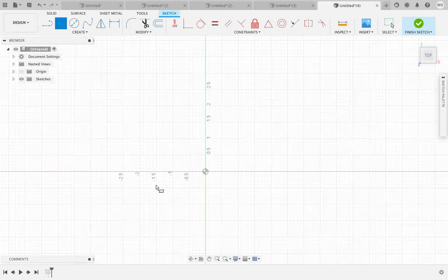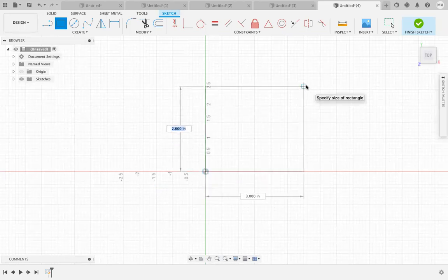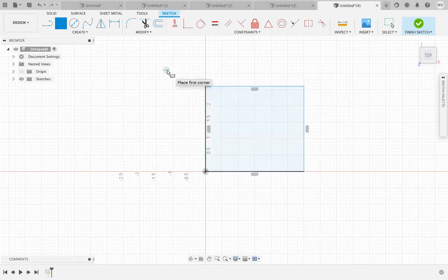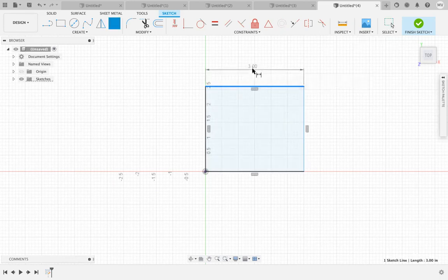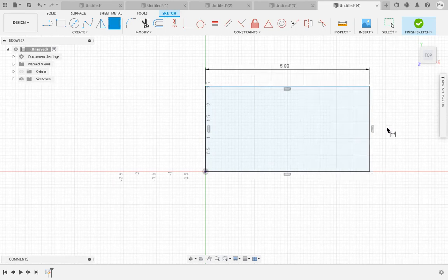We've done a couple designs in the past. And the first thing we did was we locked it to the origin. Okay, that's fine. We can do that. If I click, I can then dimension my sides by using the select tool, clicking one of the sides and pressing the letter D. That will give me a dimension and I can type 3, 4, 5, whatever I want. That will change that. And we can see the sides that are black are locked in place.